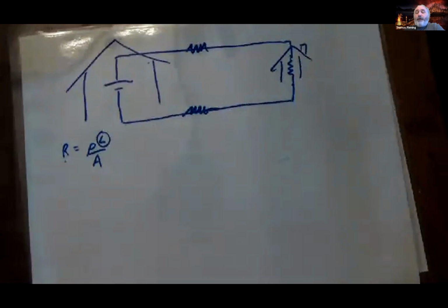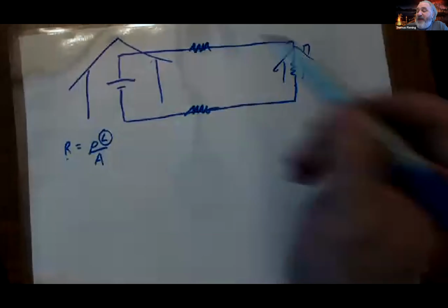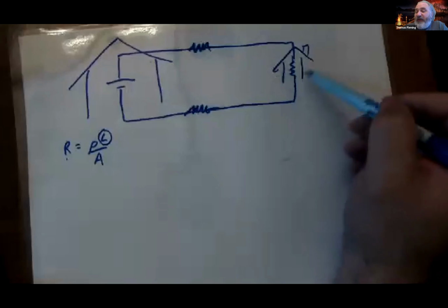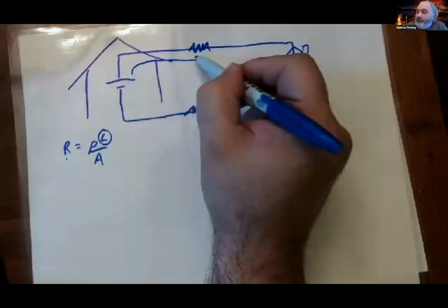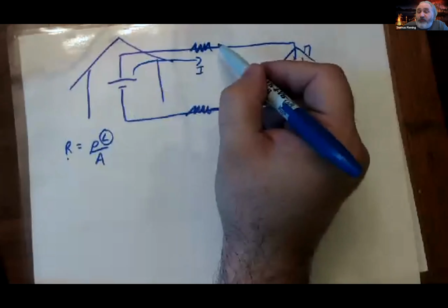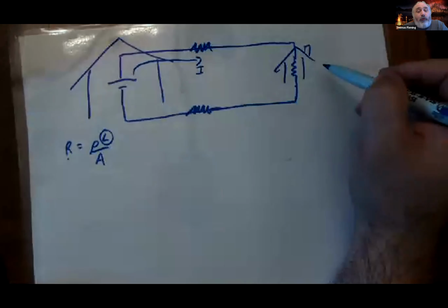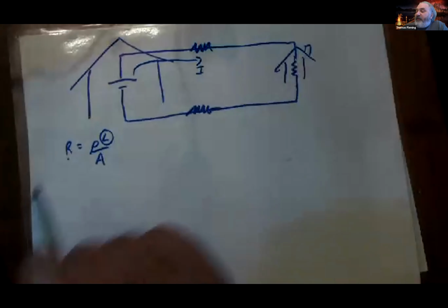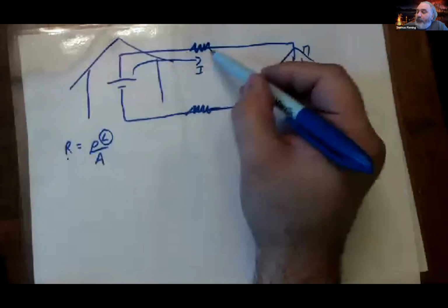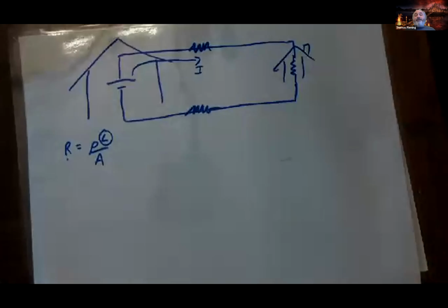And here's why that's important. You're sending current out of your power plant, and the problem is every bit of current that you get to this house has to travel along the way through that resistor. There's no other way to get the current from the power plant to your house with direct current. And that means that as the current travels through that resistor, there's a voltage drop, right? You're burning energy just to get the power to your house.